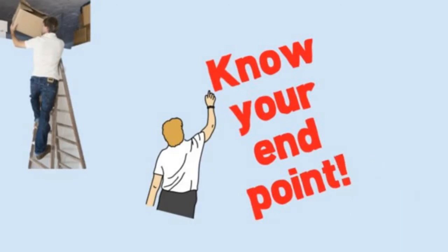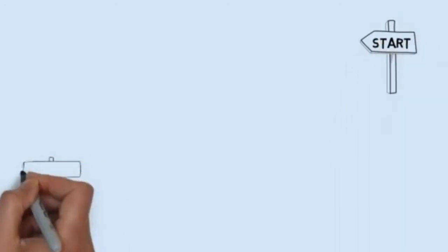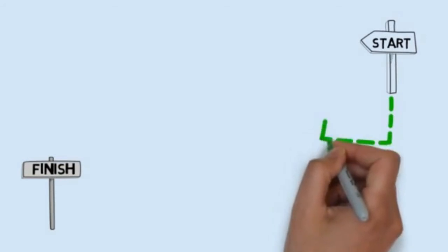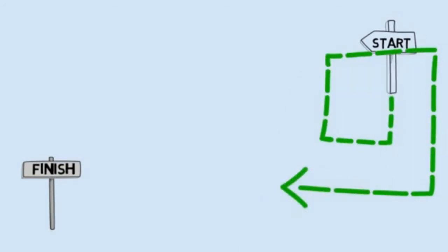You can always shift it after it's down. 5. What route do you have to follow while carrying or moving the load? Check the path from start to finish. Are there any tripping hazards, trash, or debris on the floor? Any holes that could break your ankle?